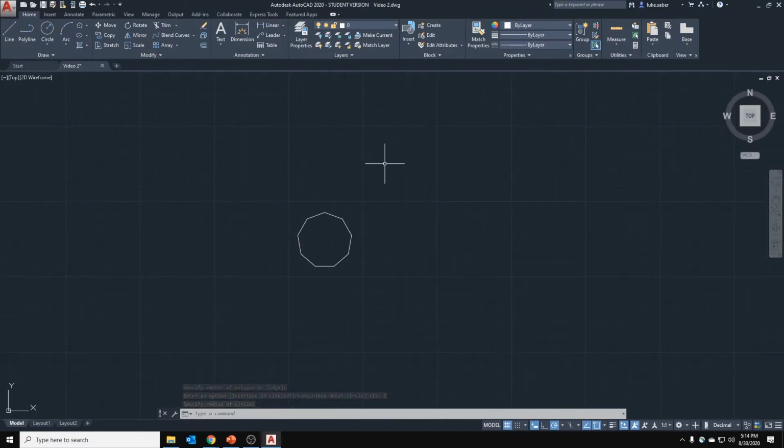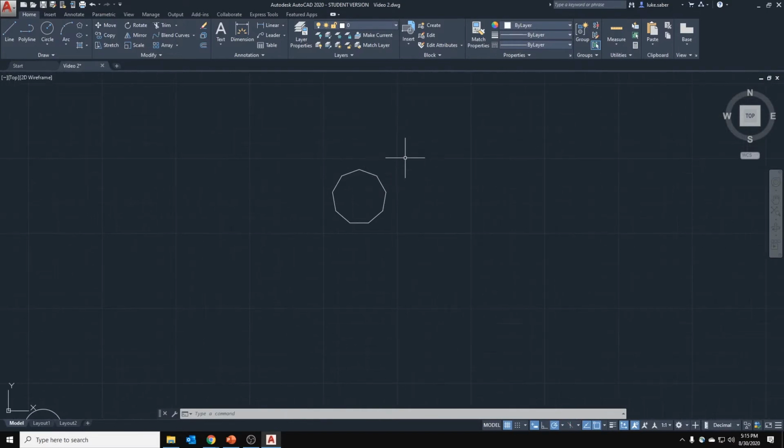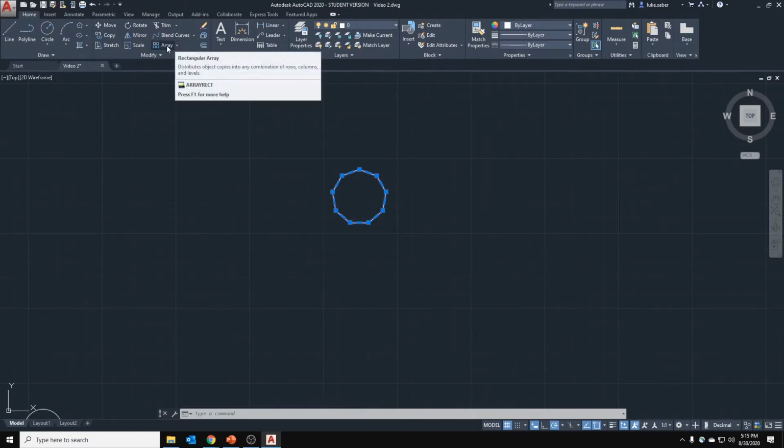Now, what if I want to make a bunch of them in a certain rectangular direction? So within 90 degrees, like a grid, right? Like imagine if you had this on an XY axis and you wanted to repeat it every 1 inch in each direction. We are totally allowed to do that, and it is awesome to know how to do that. So let's copy this, and we can click array. You can just click this.